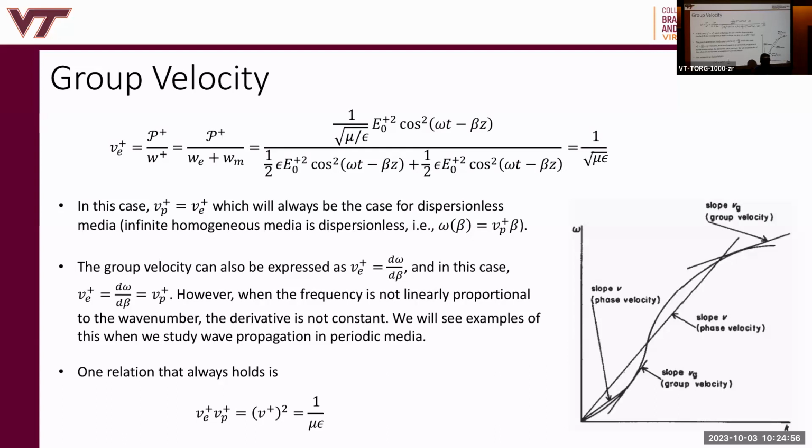So if it's not a guided mode, it's a wave which is traveling in free space and scatters off of some other object. Antennas are like that, or radar cross section or anything like that. Scattering is what we're going to cover in this course first, in this semester. Free space is a dispersionless medium. So it's still a wave traveling through a medium, but that medium is free space typically, or homogeneous space, and therefore it has no dispersion. So we don't worry about dispersion plots like this, dispersion diagrams. We'll study these much more in depth next semester when we do guided waves.